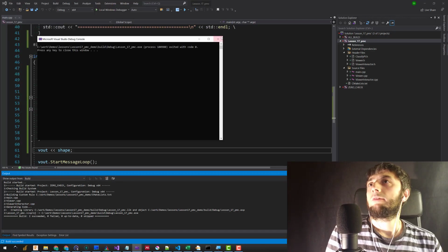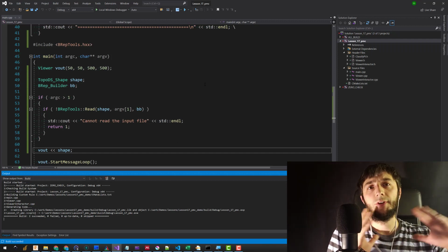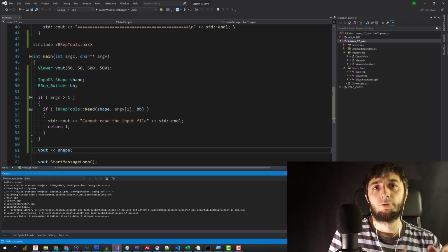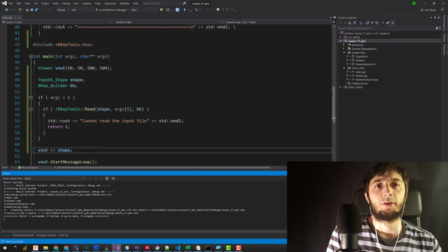So here I want to have a bounding box of my shape in order to sample not the whole infinite space, but only this bounding volume, like this stock volume around my shape. Because I need to have a limited domain in order to do this point membership test.